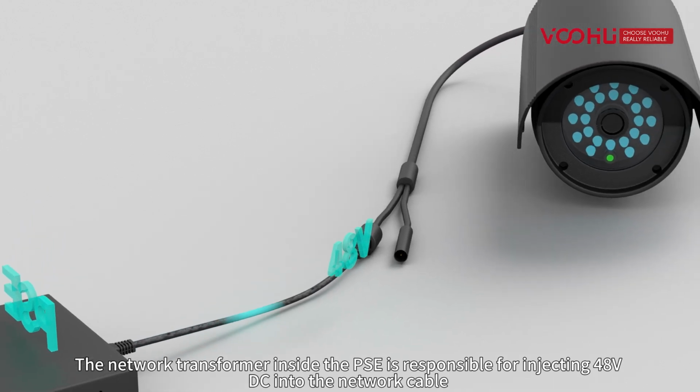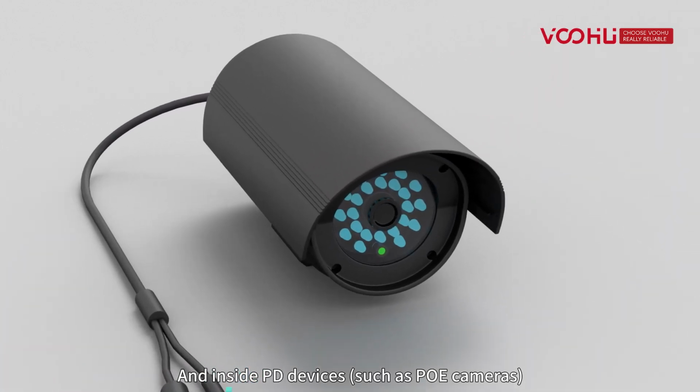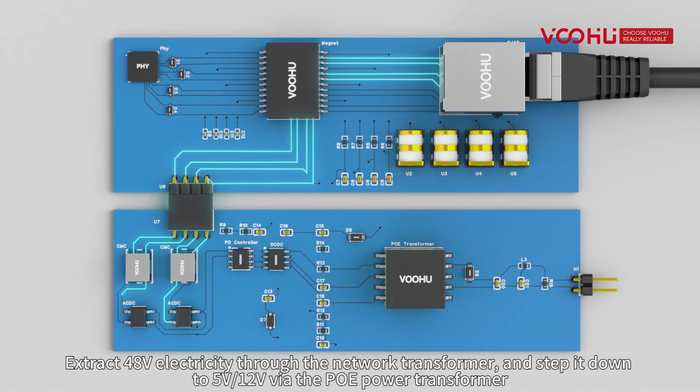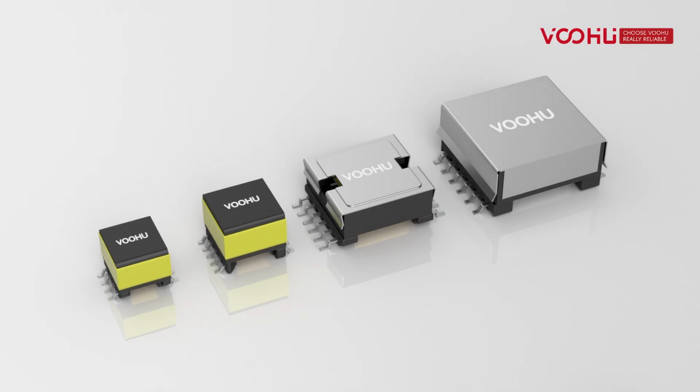DC into the network cable. And inside PD devices such as PoE cameras, the 48 volts is extracted through the network transformer and stepped down to 5 volts or 12 volts via the PoE power transformer.